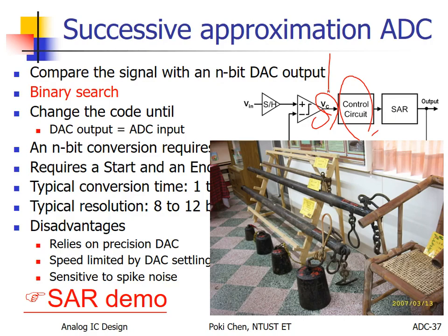Enough or not enough. So the input for the control circuit actually is binary. And then you need to control the ADC. How to turn it on or off? Still, the control bit, I mean your output, is also 1 or 0. So it means the control circuit is fully digital instead of analog.